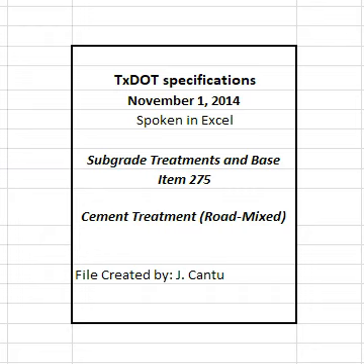4.6 Finishing. Immediately after completing compaction, clip, skin, or tight blade the surface of the cement-treated material with a maintainer or subgrade trimmer to a depth of approximately 1/4 inch. Remove loosened material and dispose of it at an approved location. Roll the clipped surface immediately with a pneumatic tire roller until a smooth surface is attained. Add small increments of water as needed during rolling. Shape and maintain the course and surface in conformity with the typical sections, lines, and grades shown on the plans or as directed.